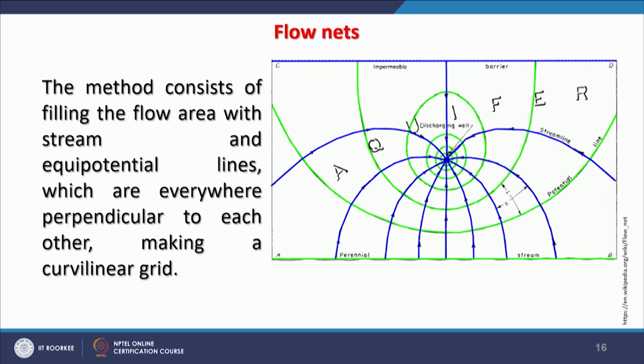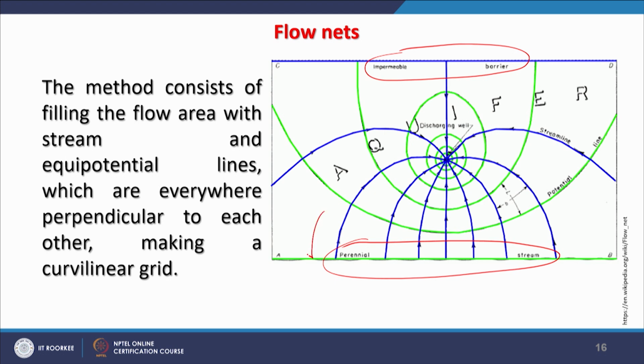That means these barriers, this is another important thing which I want to emphasize here. This is the barrier in the sense that sometimes it is getting water, influent, and sometimes it is effluent. In this case, this is influent, providing water to the aquifer. In case of effluent, the water will be coming towards the river.